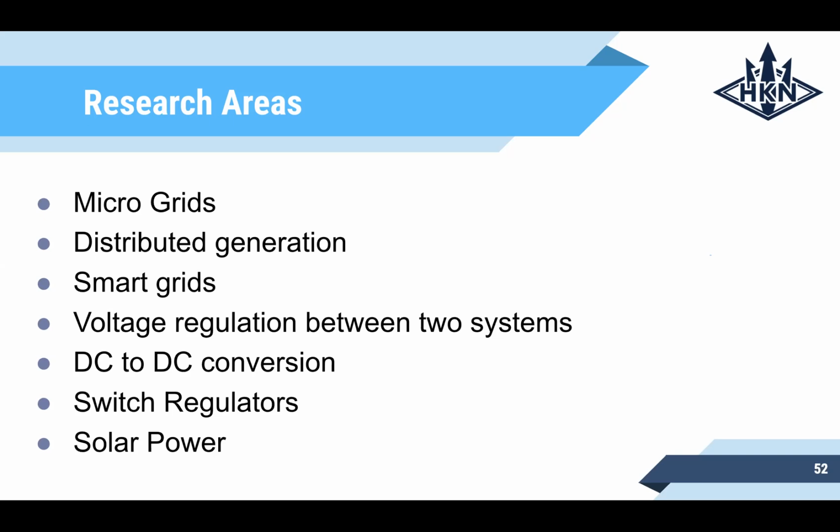So there's definitely a lot of research available to figure out new ways to do things or focus on existing things like line insulation coordination, which is essentially when lightning hits a tower, you detect where faults would occur and design the system so that it doesn't create a fault. And that deals a little bit with traveling waves like in 107, just because you have to see how the voltage and current waves are going to propagate throughout your whole system. So you learn more about that in 128C.